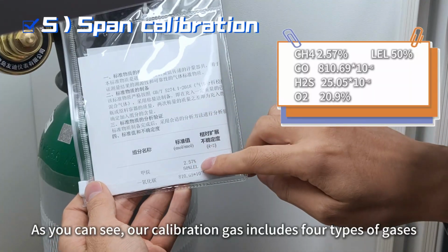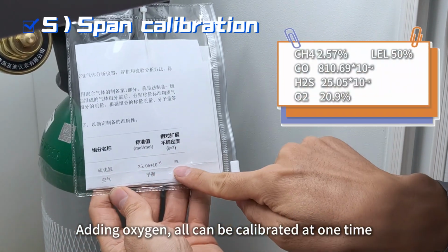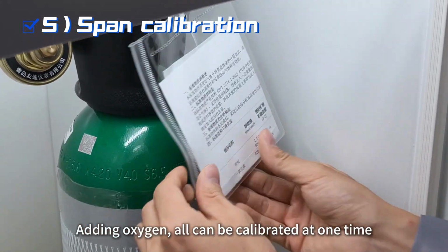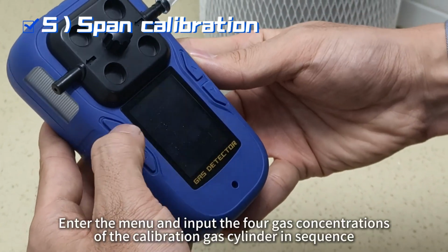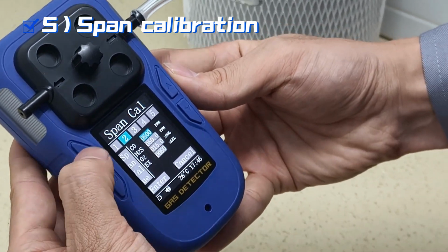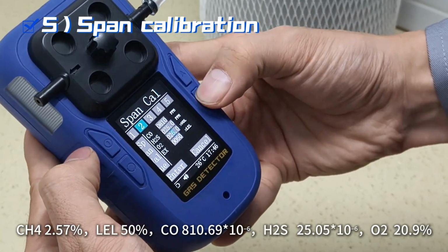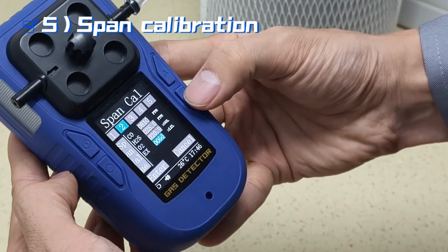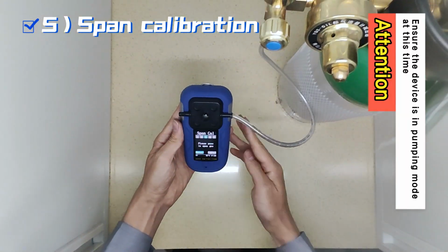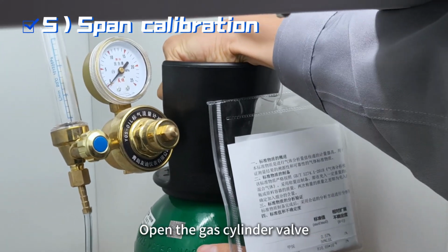As you can see, our calibration gas includes 4 types of gases. Adding oxygen, all can be calibrated at one time. Enter the menu and input the 4 gas concentrations of the calibration gas cylinder in sequence. Ensure the device is in pumping mode at this time. Open the gas cylinder valve.